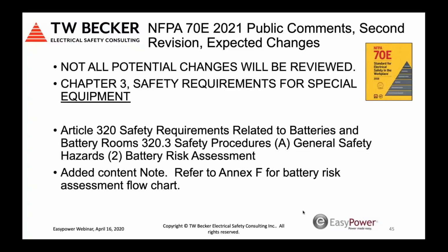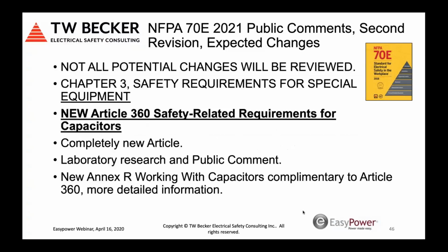And I think this might have been the majority, or what I would, in my opinion, classify the most important changes. For Article 320, requirements related to batteries and battery rooms, safety procedures, general safety, battery risk assessments. There's actually a flow chart for battery risk assessment that's been added to Annex F. And it's an excellent visual tool with respect to doing an electrical hazard risk assessment, hazard ID for batteries.